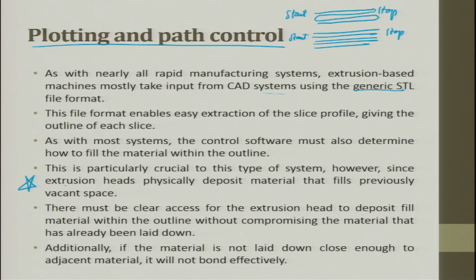However, since extrusion heads physically deposit material that fills previously vacant space, there must be a clear access for the extrusion head to deposit fill material within the outline without compromising the material that has already been laid down. Additionally, if the material is not laid down close enough to the adjacent material, it will not bond effectively.